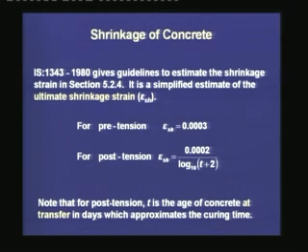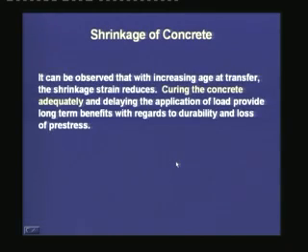0.0002 divided by the logarithm of T plus 2, where T is the age of concrete at transfer in days, which approximates the curing time. Here also what we observe is that if we increase the curing time and delay the transfer of pre-stress, then T will increase and hence epsilon SH will decrease. Thus, with increasing age at transfer, the shrinkage strain reduces.